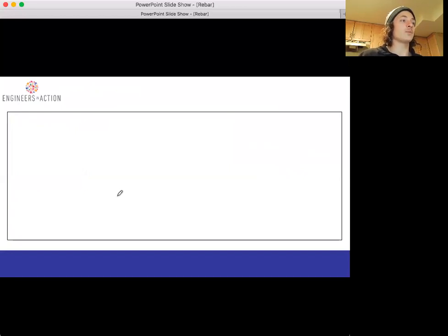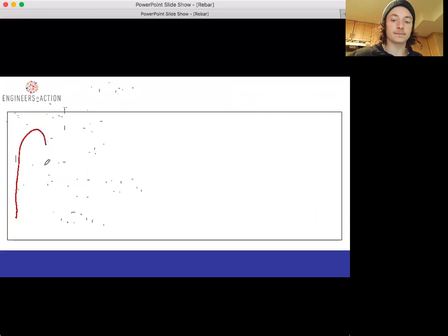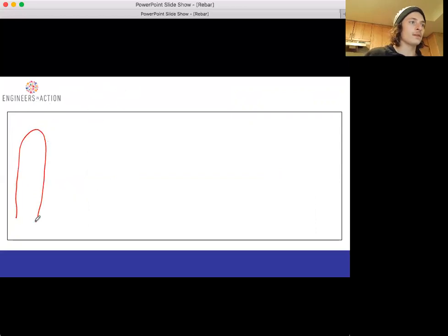There are multiple ways in which we can create waste here, so it's important to consult your in-country manager ultimately on your final numbers. But first, in order to transport this bar in trucks, let's say, as we did before, it's bent into a U shape, and rebar is structural and cannot be unbent. So some is lost in the U shape at the end of the bar.